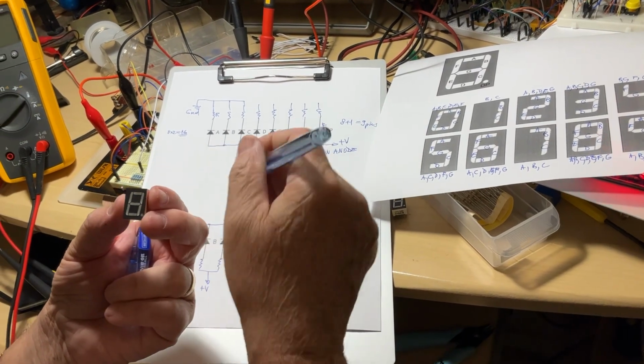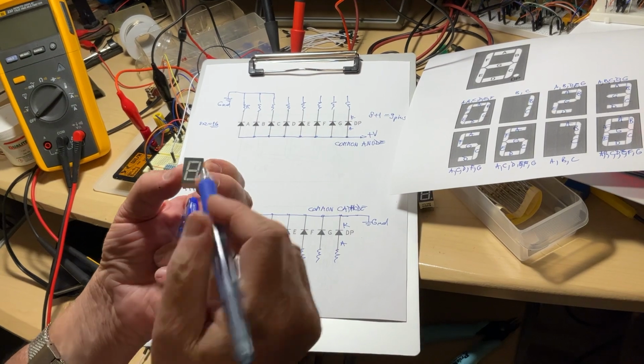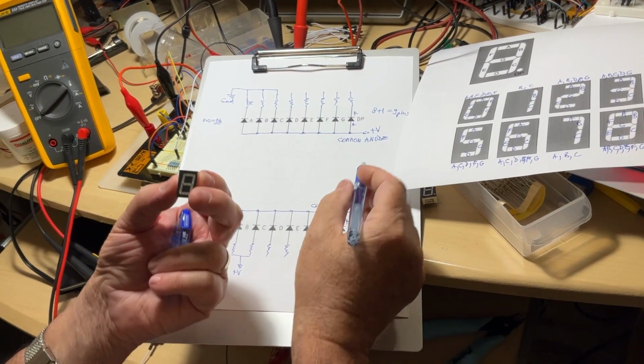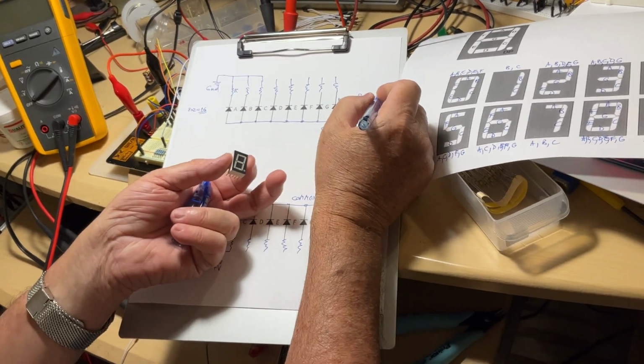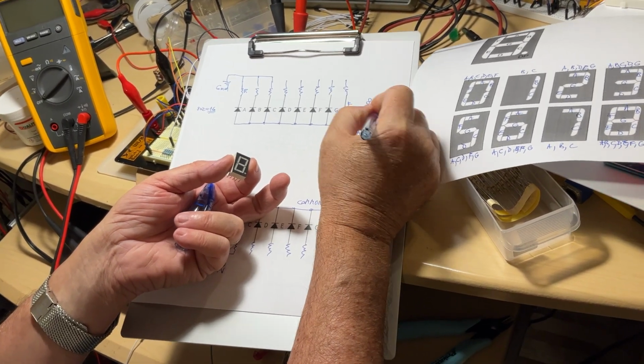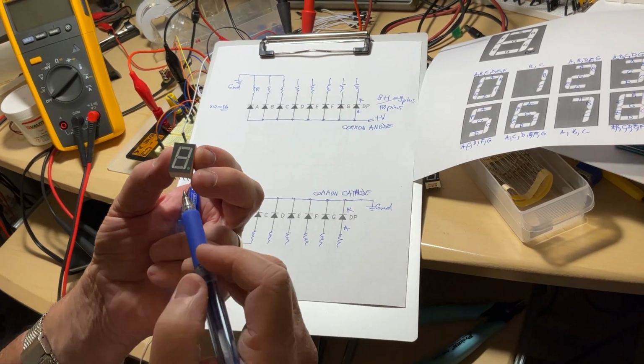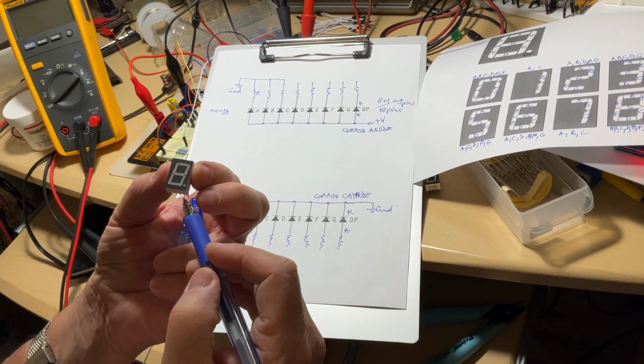So the designers making the printed circuit boards will have access here in the bottom and in the top to the same anode. This is why, instead of having 9 pins, it has 10 pins or terminals, because the common anode is repeated in the top and in the bottom.